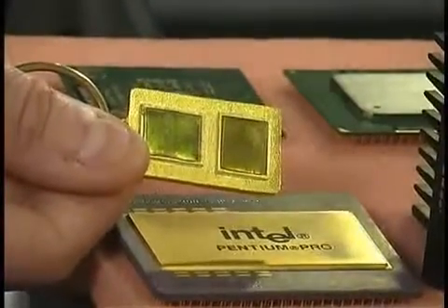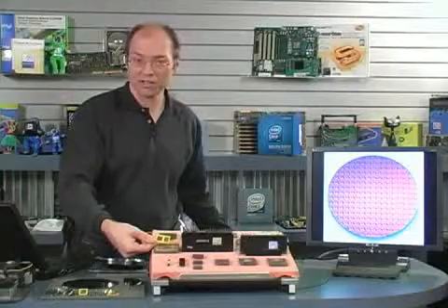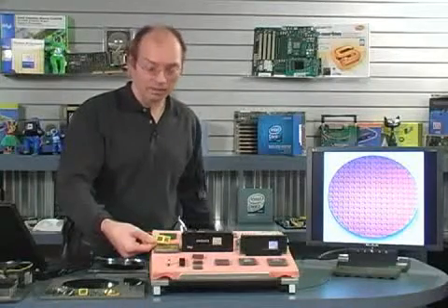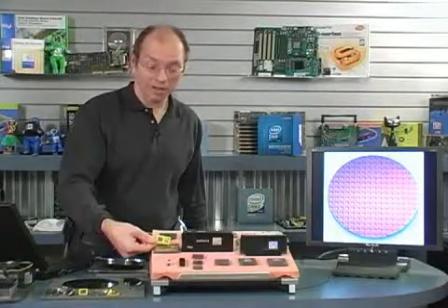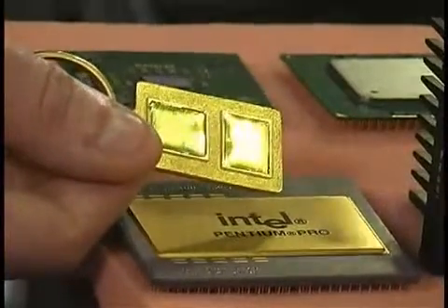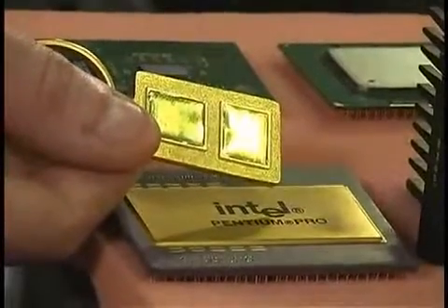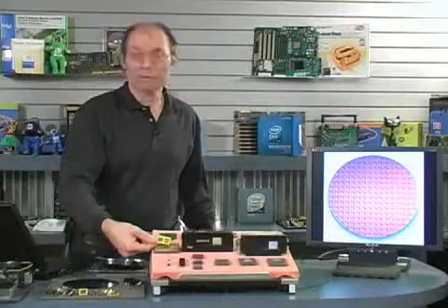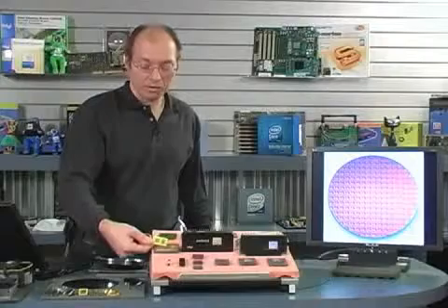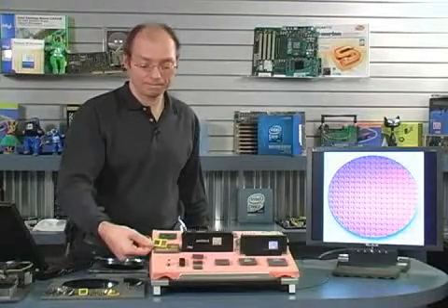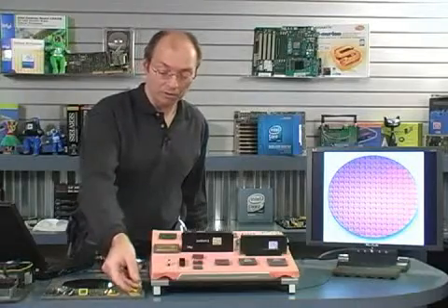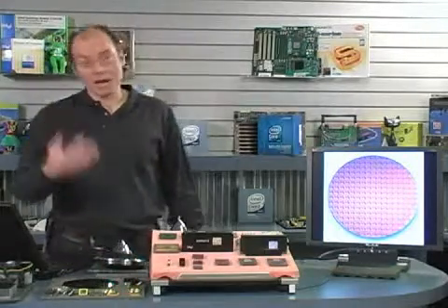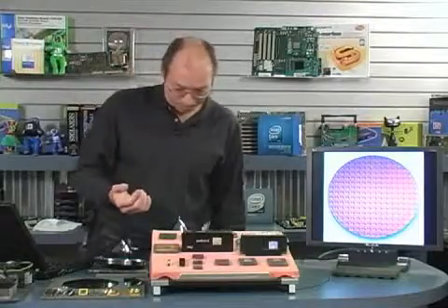One of them is the actual processor chip, and it has its own built-in level 1 cache memory. The other chip next to it is a level 2 cache memory chip. Prior to this, the level 2 cache had been on the motherboard. Now it was part of the processor, but it was still a separate chip. This dual chip in a package processor was very expensive to produce, so it wasn't very popular.